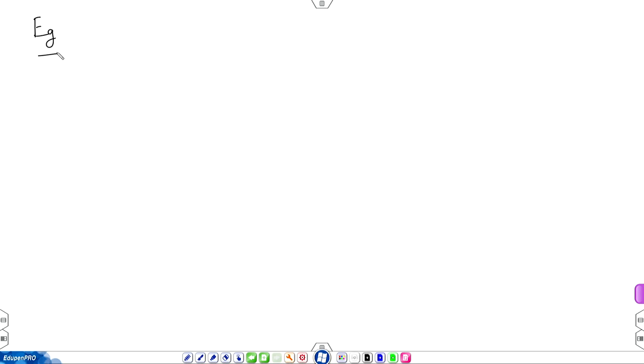So, we solved the mass balance equation and we got one result u1 equal to u2. What is u1? It is the average velocity in the axial direction on the inflow plane equal to average velocity in the axial direction on the outflow plane. Two are equal. If they were not to be equal, there would be accumulation of mass inside, resulting in unsteady effects. There would be continuous change in density. But since we stipulated steady flow, u1 became equal to u2.